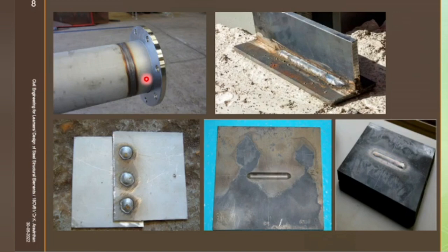All the grill work is made by using which weld? Fillet weld only. If you are looking into which one? Groove weld. How the groove weld will look is, you will not have one member and another member separately. There will be holes in it and it will be merged here. So this kind of thing is called groove.